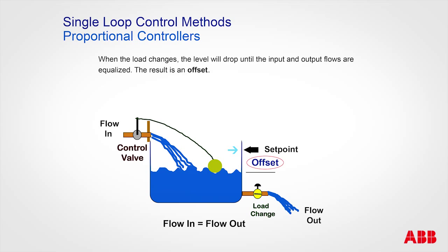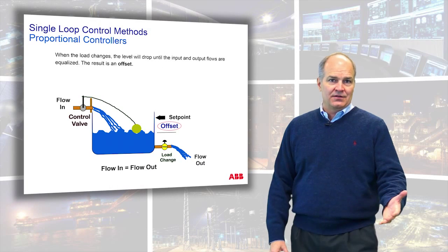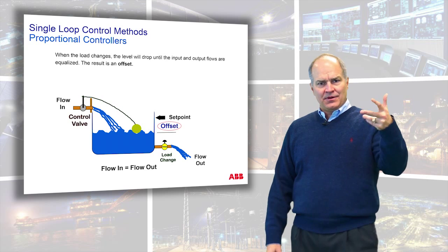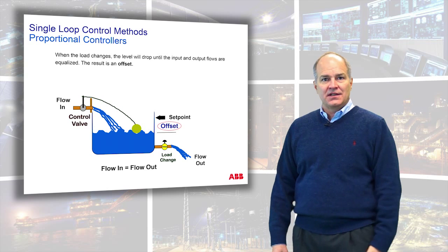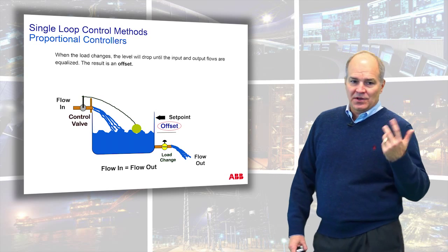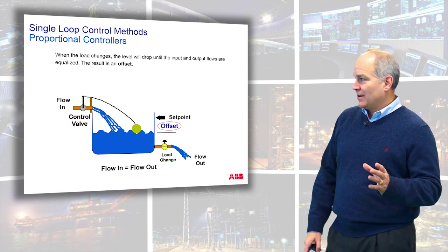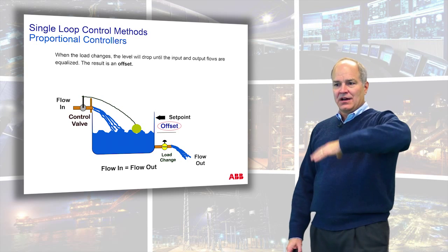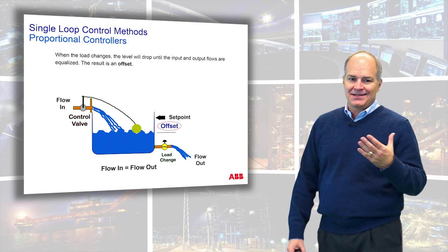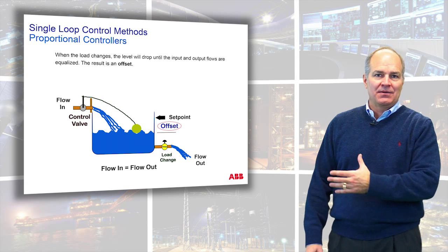So that's what's called an offset. I've seen people inadvertently block the integral term, and the set point and the measured value are just offset. Usually that's my first question: did you block the integral? So this is what can happen. There are some cases where, if you have a loose tolerance, this is fine. In today's applications, this is becoming more rare.